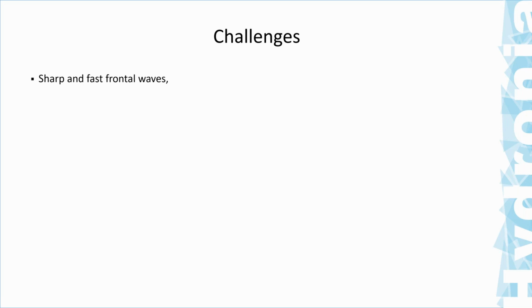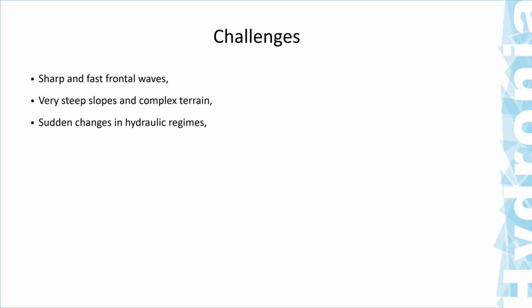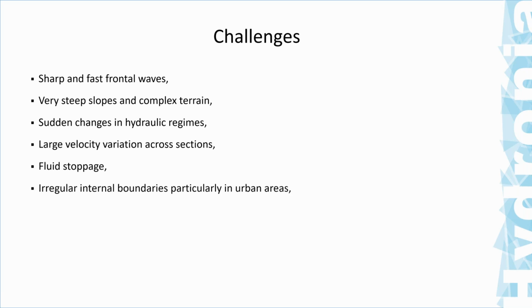So in terms of challenges, we have sharp and fast frontal waves. We have very steep slopes and complex terrain, sudden changes in hydraulic regimes. We have very large velocity variations across the sections. The fluid stoppage, the irregular internal boundaries, particularly in urban areas.